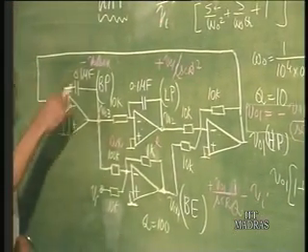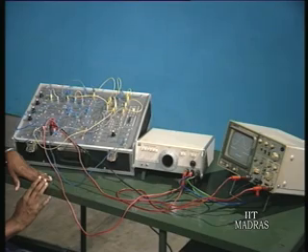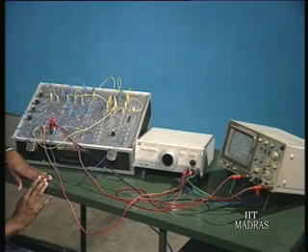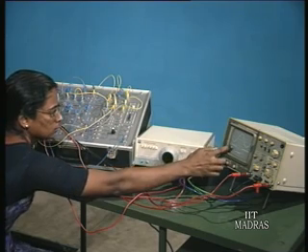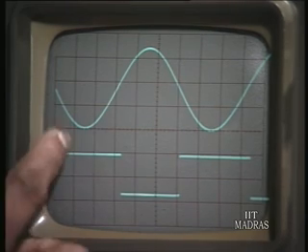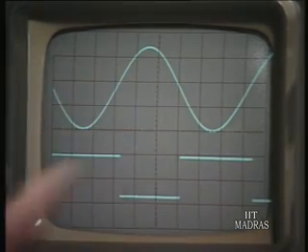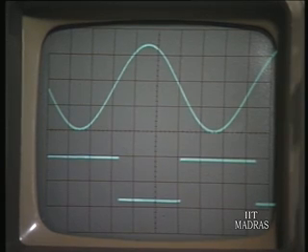She has built this entire circuit, and now you are going to see the square wave that is applied at the input. That is the input square wave, for which she has shown you the output of the band pass, which is nothing but the fundamental, amplified Q times compared to the fundamental of the square wave.